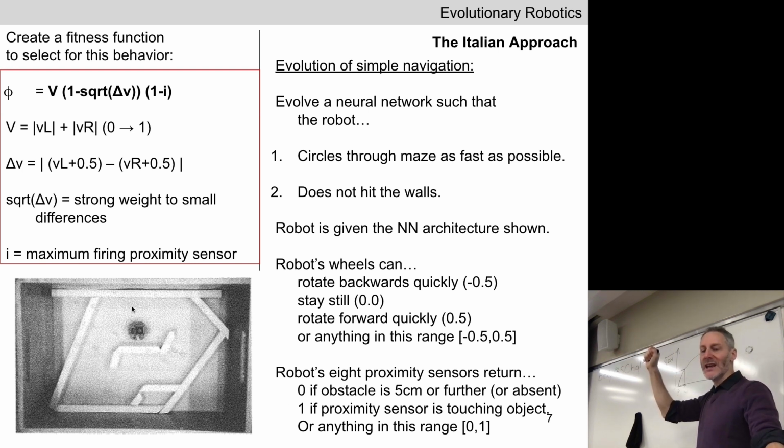The robot moves again a little bit, and they're recording all these sensor values. They look at the new set of 8 proximity values, and if there's a new value within that set of 8 that's even higher than the maximum recorded value so far, they throw away the old value and hold on to that one. So among all 8 proximity values, over the lifetime of this robot's behavior, they're looking for the maximum value of any proximity sensor.